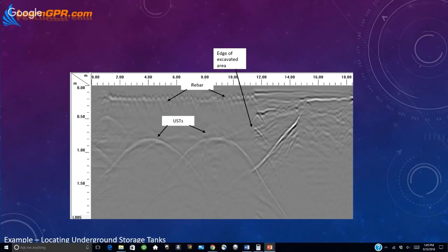Okay, so this right here, this reflection, is what we interpreted as an air wave. And so by understanding what's around you, I'll say it again, understanding what's around you and understanding how the waves behave, we were able to recognize that this reflection actually was something from the ground surface that our GPR was moving towards. And as we moved closer and closer to it, the GPR wave spreads out across the ground as well.